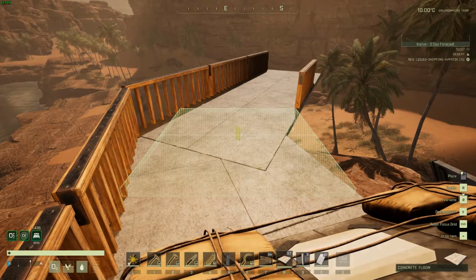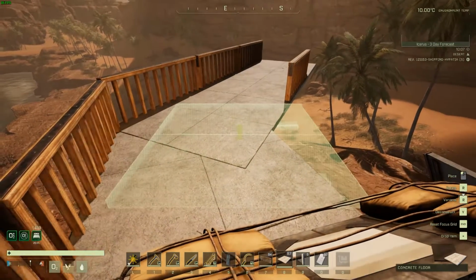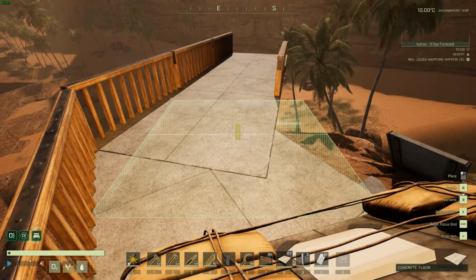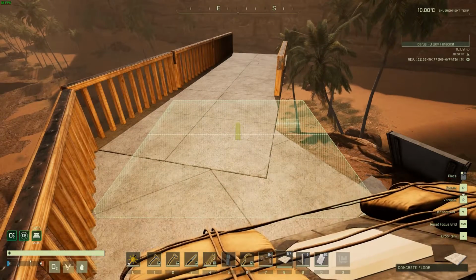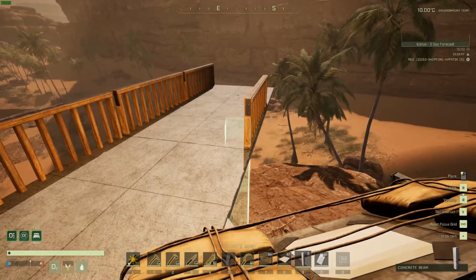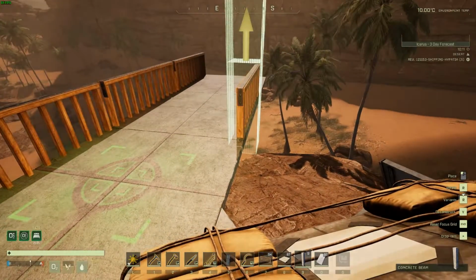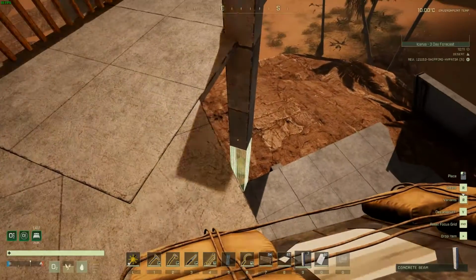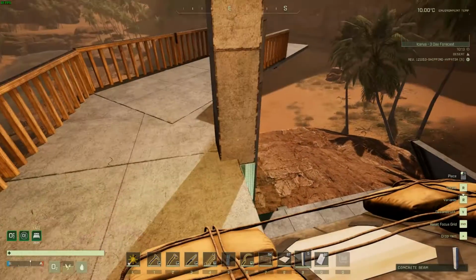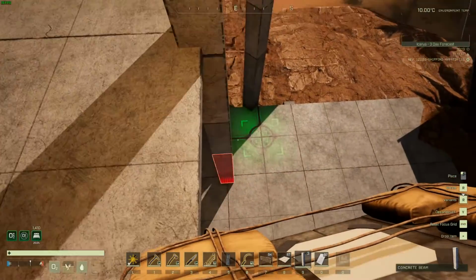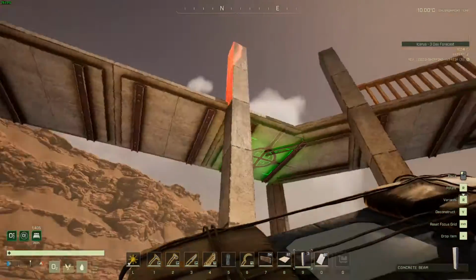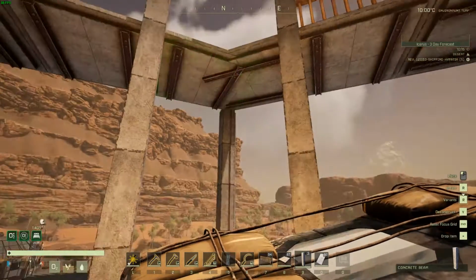But if you look at the angle of the beam here, what we're going to try to do is put a beam up over here first. So right at this spot, hit the home key to snap to my grid, and we're just going to drop a beam system there, and then another system of beams off this 90 degrees just down here, because we want to get an idea of where we have to go, right?